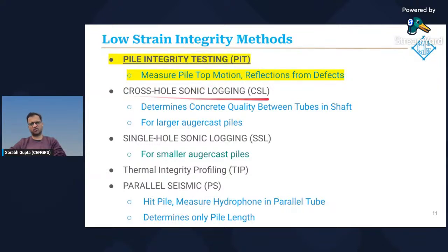So there's cross-hole sonic logging (CSL), where you install access tubes in the pile, and you can actually test down the pile. You can test to check the concrete continuity. The single hole and multiple hole sonic logging. Thermal integrity profiling is coming up.